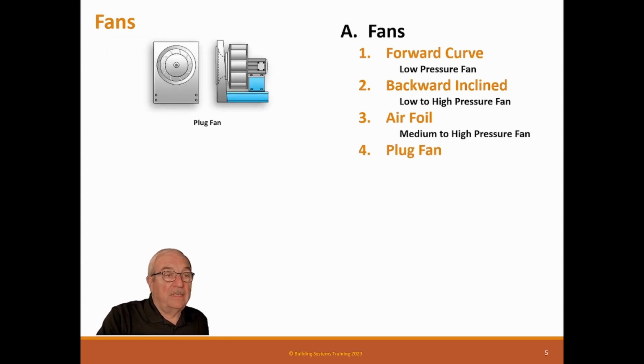We have what's called a plug fan. A plug fan is designed to sit in a plenum space. And what you do is this would be the plenum right here. And you install these, and they will suck the air in through the plenum wall and pressurize the plenum. Okay, so